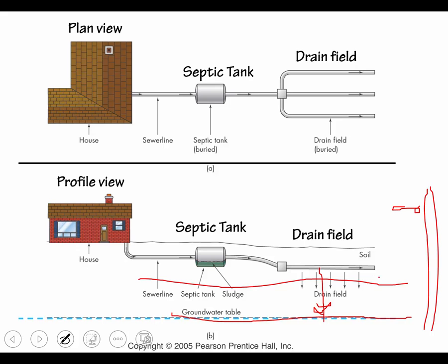The other thing is what type of sediment is above the water table. Is it impermeable or is it permeable? You want it to be slightly permeable. You don't want it to back up, but you don't want it so permeable that it'll just soak through without retardation. Yes, ma'am. That rainfall, is that just filtered sewer? Yep. Water? Yep. It's the same thing that would go into a sewage treatment plant in the city.